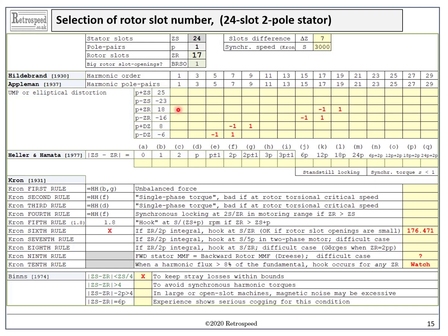And I'm afraid we have to contend with another theoretical complication at this point. If the winding is balanced and contains only odd-order MMF harmonics, we are never going to find two waves differing in pole number by 2. For example, the 23rd and 25th differ in pole number by 4, because they differ in pole pair number by 2.